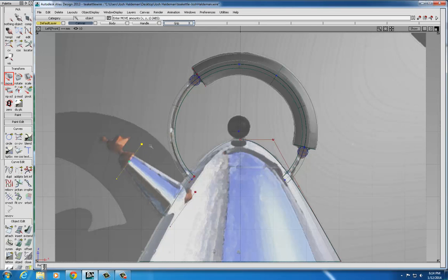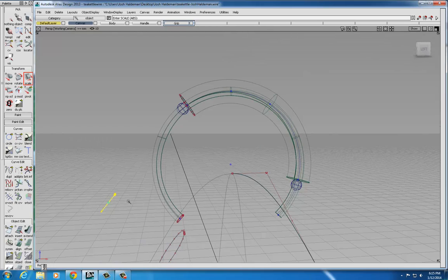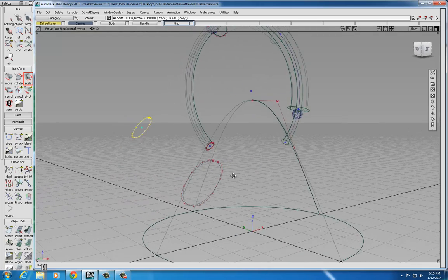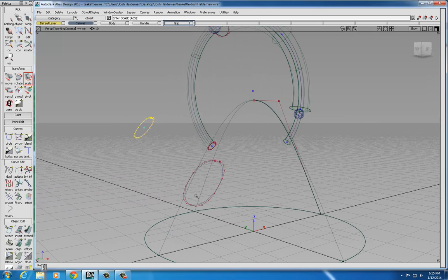And here you can tell how close you got it to being aligned correctly. If it's slightly off, you can correct it. Again, move it into position, rotate it down. Make sure you rotate around the right axis. The Y is correct. And then to scale it all down, make sure you're on the scale tool and use your left mouse button to scale it left and right and up and down so that it's smaller. Now I've effectively got these two circles that are roughly aligned with one another.